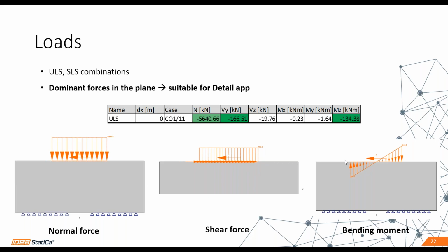Generally you have two forces with different orientation, and you need to create from this bending moment this type of load, where the intensity for 1 meter is 810 kilonewton per meter. You can calculate it based on stresses or from a really easy equation, and you will get this shape. How to do that in detail.